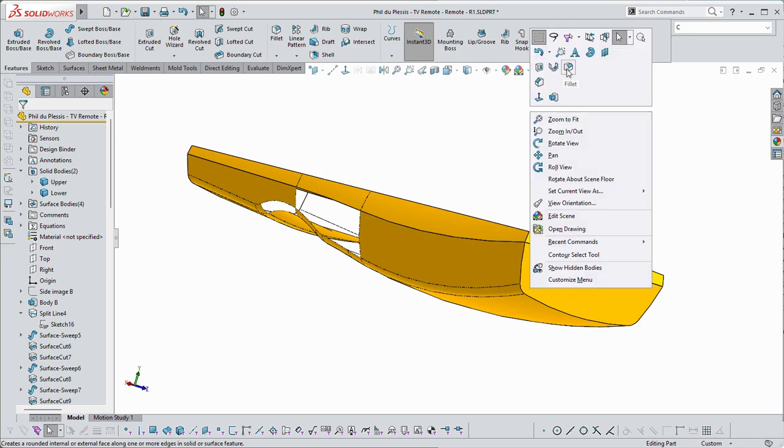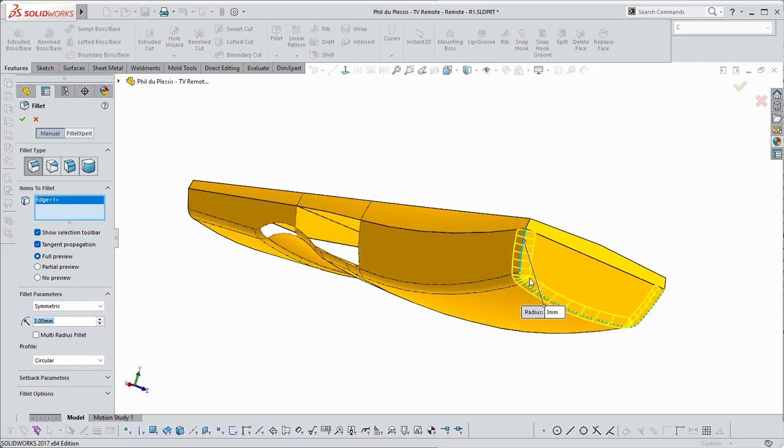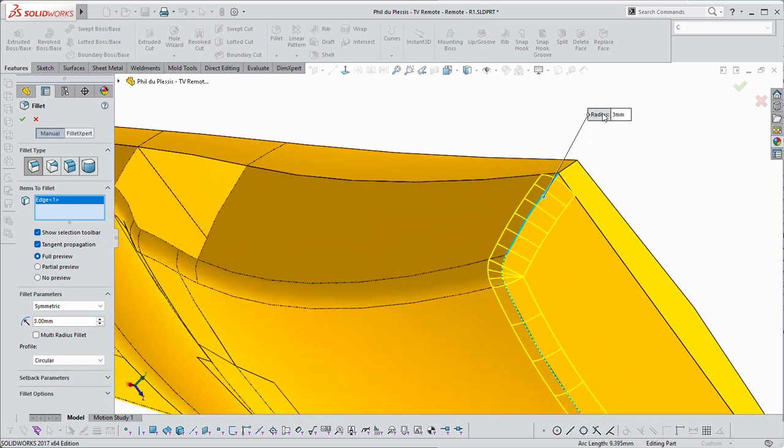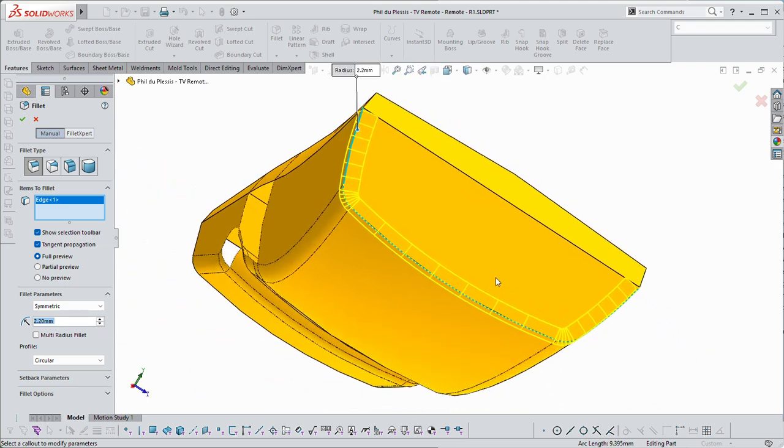Right, so the next fillet is this one here, which I'm going to make a lot smaller than that one because we want to avoid, especially for this exercise, any three-sided cap to a fillet. So that's three-sided. That means that little point there is a singularity. I don't want that. I want to know that you know how to avoid that. It doesn't look good. It's difficult to machine. There are all sorts of problems with it. So you should try and avoid it as much as possible. You can't always avoid it, but you should, for this exercise, for me, avoid it.